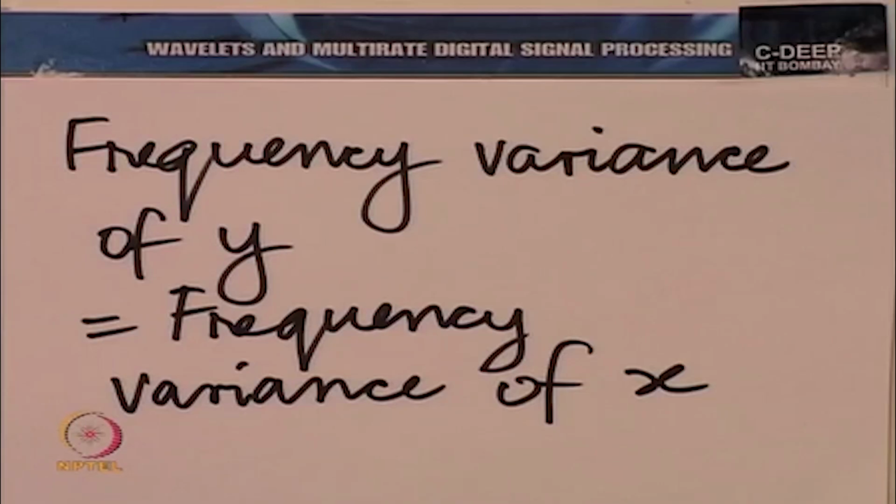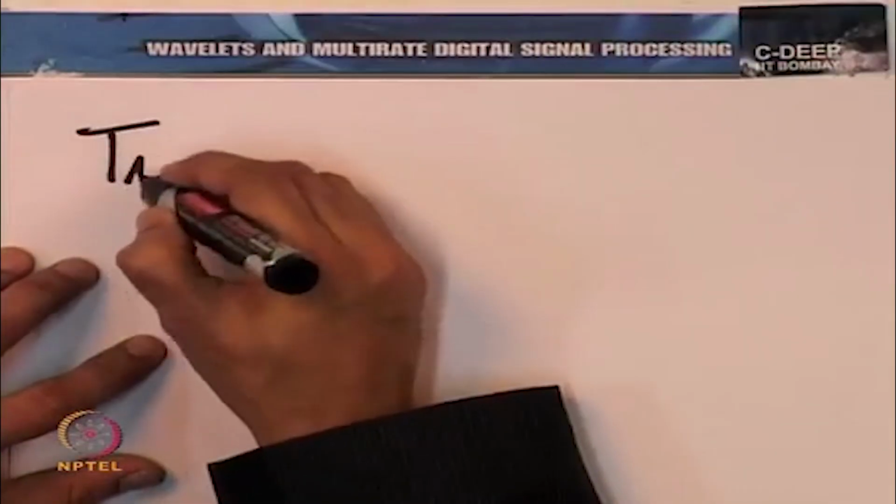So far so good. So, we have taken two dual operations, the time shift and the frequency shift, and in both of them we have had no change in the variances, and obviously, when there is no change in the variances, there is going to be no change in the product of the variances. So, the sigma t squared sigma omega squared product, which we shall now give a name, we will call it the time bandwidth product. So, we introduce the term of a time bandwidth product.